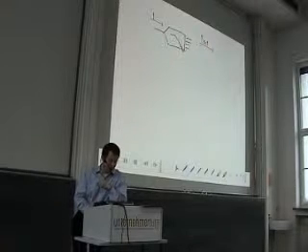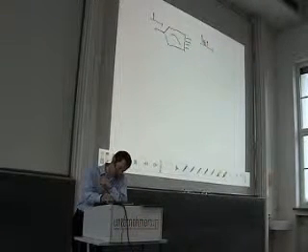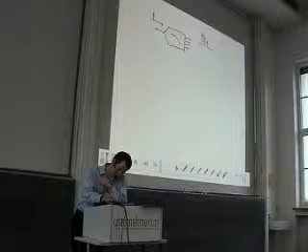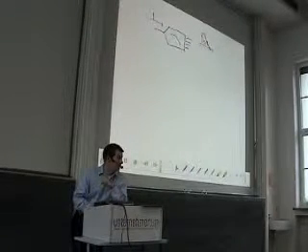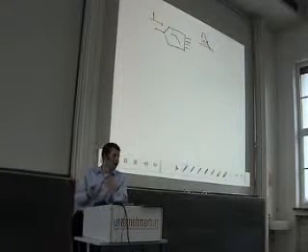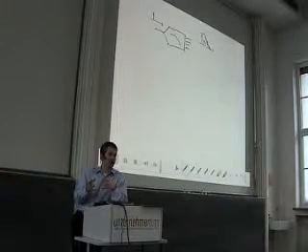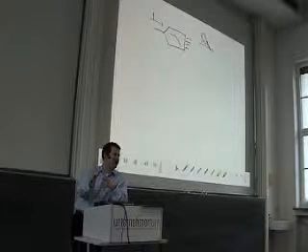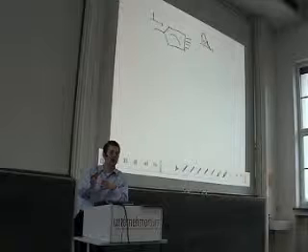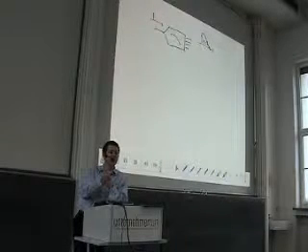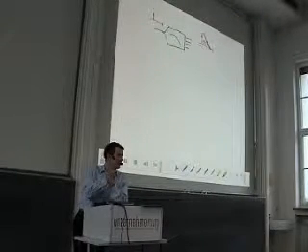What happens then is that we damp the harmonics with this low pass. So when we measure this device, we look at the harmonics and say, hey, wow, the harmonics are quite low. So the system has to be very, very linear because there is only small harmonic distortion.